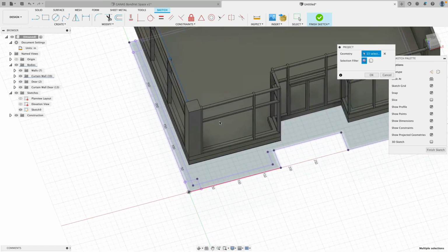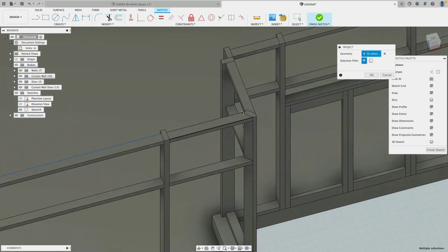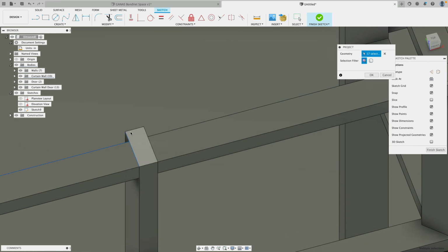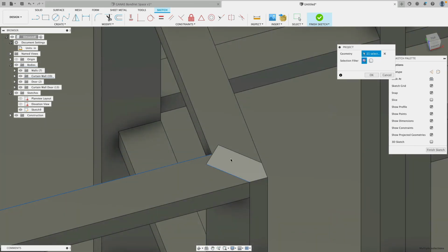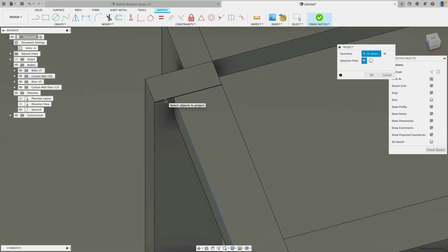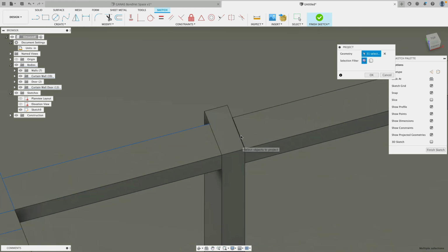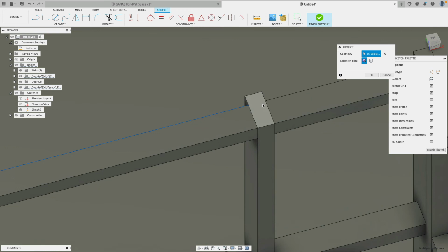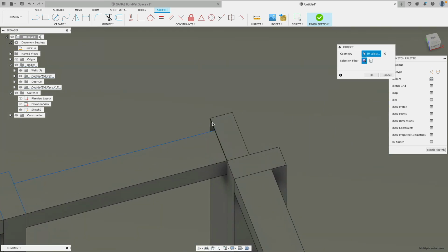There, very good. Look at that, how beautiful this actually brings everything over. So we're not drafting a new plan view, we simply create it based on the work we did, and we simply project everything in. So much easier, more effective. And here, you see I just simply continue selecting all these edges. Not complicated.